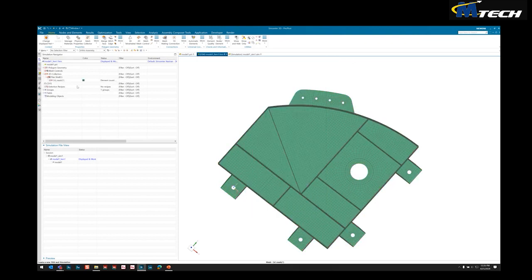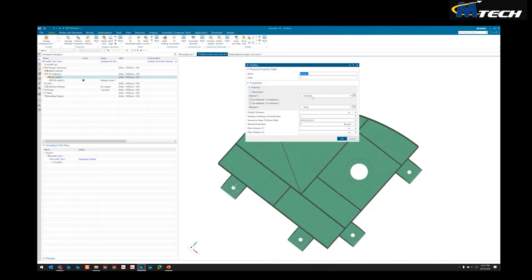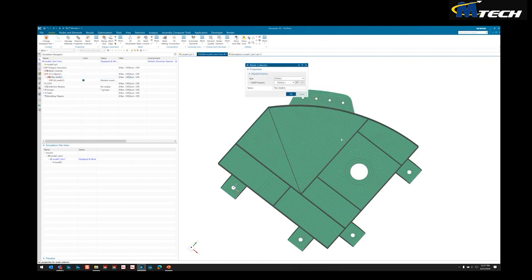So inside this 2D collector, we've got the property and then the mesh characteristics. So in our property, if you had inherited material from the solid, it would use that. Or you can go here and define your material. That's where you do that. So that's what that script is going to modify, that field right there.